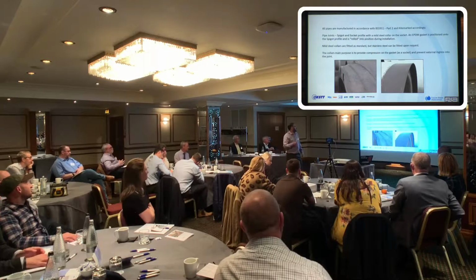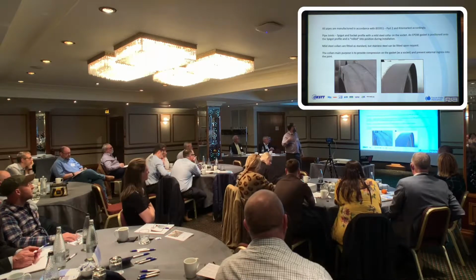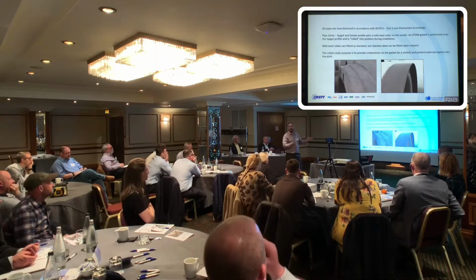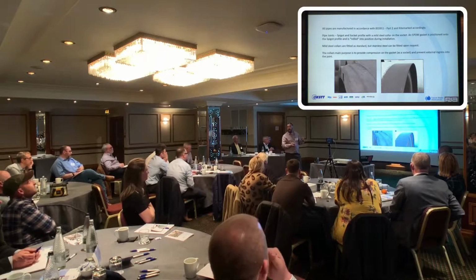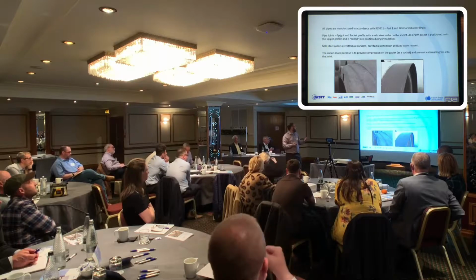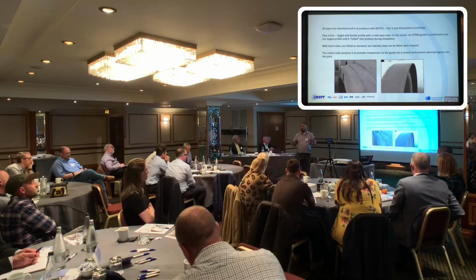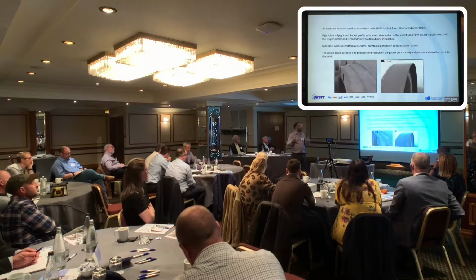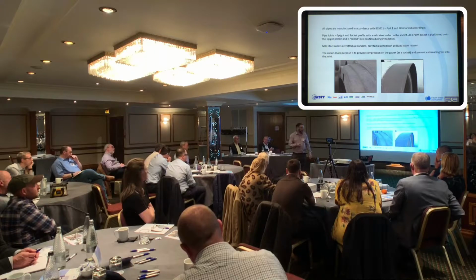All the pipes are manufactured to BS 5911 and moulded accordingly. It's a spigot and socket profile joint with this mild steel collar, which you then fit an EPDM gasket onto the spigot profile, and then this is rolled into position during the installation. Mild steel collars fitted as standard, but we can also fit stainless steels or other materials if needed. Now the collar is always seen as a magic, a specific thing for the jacking pipe, but in reality it's just there to provide a compression on the gasket and also to prevent anything from externally coming into the joint.